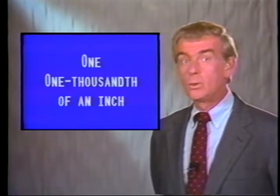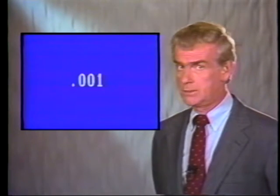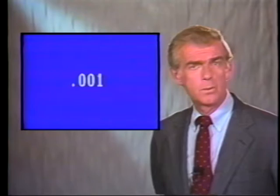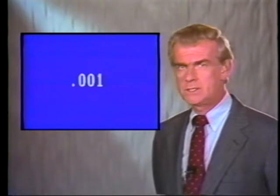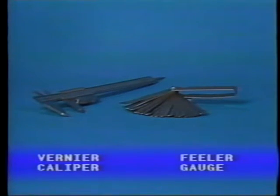To properly rebuild an engine, you must be able to use many measuring instruments and gauges. As a general rule, the tools must be capable of reading accurately to 1/1000th of an inch, which is written as .001. Though we will discuss how to read a micrometer in this question, you should be familiar with other measuring instruments such as dial indicators, bore gauges, vernier calipers, and feeler gauges.